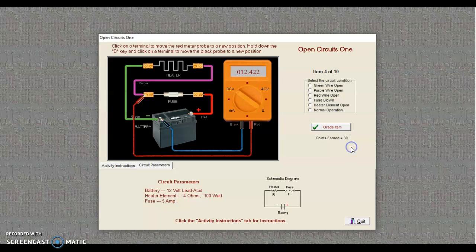One last one. I said one last one last time, but I enjoy doing this. Again, remember to reset. So we have 12.2 at our source. We're going to look on this side of the fuse to begin with, strategically. Now notice we're going straight from 12.2 to 0. So I know that I have to move this way with my probes. It's a possibility the fuse is blown here. And it sure is the case.